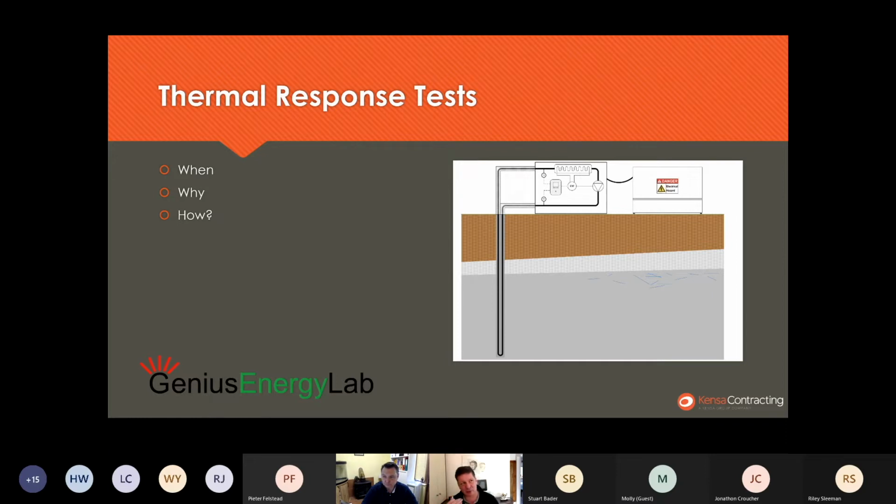Now, that's not to say we're not experimenting and learning as we go. For example, we might drill a test bore to 300 meters, but actually that last 40 meters was a nightmare. So we install the loop to 260 meters and measure that. So there are some variances in that, but ultimately the bottom of that loop wants to be where we're going to be putting the bottom of the rest of the ground loops on this site.